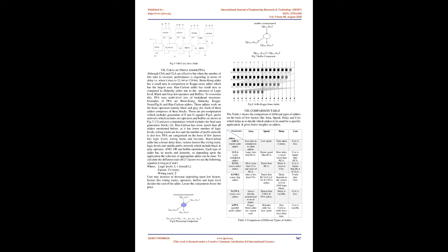Delay is variable. As the number of inputs increases, delay also increases. Also, CSVA is composed of RCA, so the delay is more. Cost is less, nominal cost, as its basic component is RCA, but cost may increase if the number of inputs increases. 7. Parallel prefix adder, PPA.